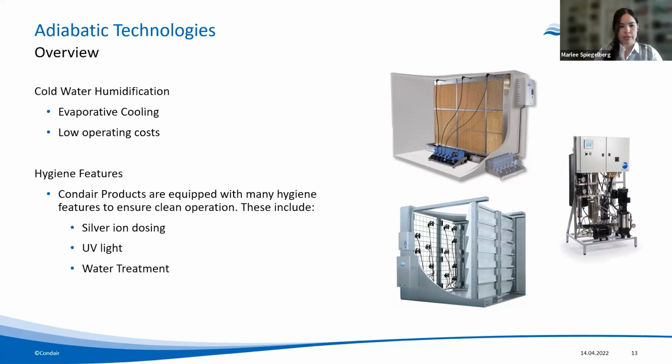Just another point is hygiene features. Condair products are equipped with many hygiene features to ensure clean operation of our adiabatic or cold water systems. Again, you're not boiling that water. So these include silver ion dosing, UV lights to break down the bacteria or cells within the water, and water treatment, so that reverse osmosis system.